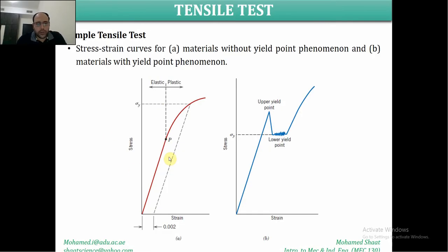Alright, so as we showed in this video for these two material samples, for the aluminum case, we obtained that the material has a smooth transition from the elastic region to the plastic region, and there is no specific yield point that we can identify. But for the case of the steel material sample, we end up with the yield point, or the yield region was clearly seen by the sudden drop in the force, and we obtain this odd behavior of the material within this yield region.